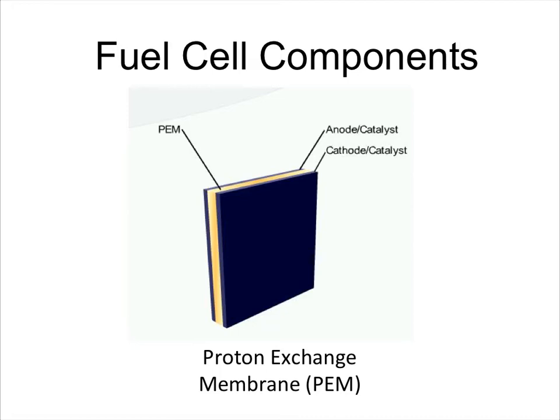The anode is the electrode at which oxidation, which is the loss of electrons, takes place. In a fuel cell, the anode is electrically negative. The anode is composed of platinum particles uniformly supported on carbon particles. The platinum acts as a catalyst, increasing the rate of the oxidation process. The anode is porous so that the hydrogen can pass through it.